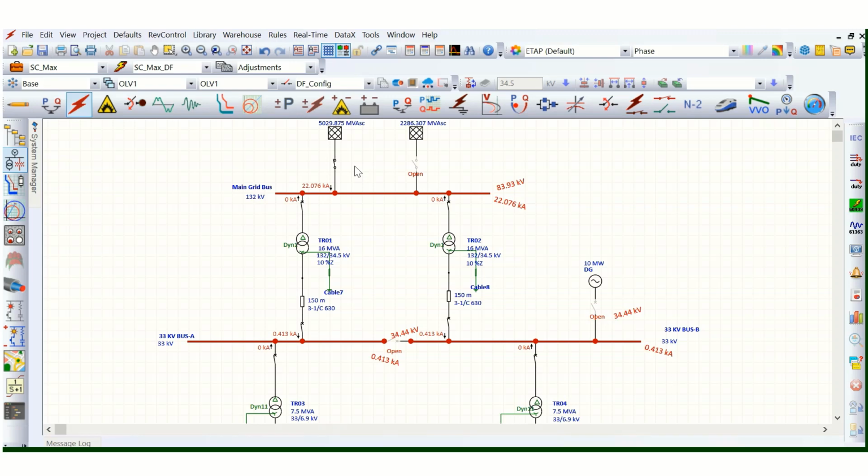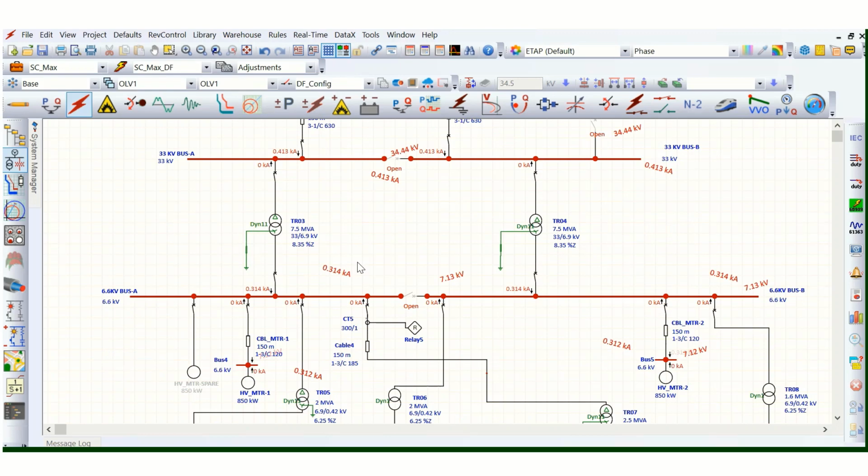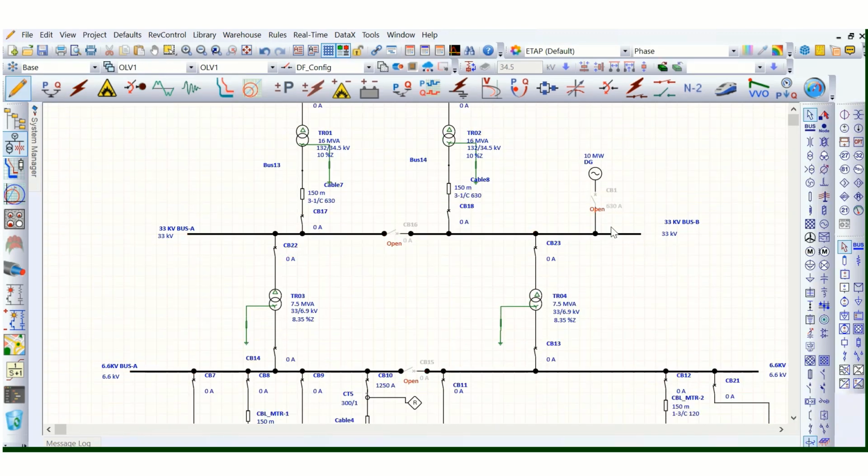So that instantaneous setting will be there actually. So the fault will be cleared instantaneously. So there the solidly grounding system can be used. We should not use any resistance or reactive grounding system. So how, let's model that one.